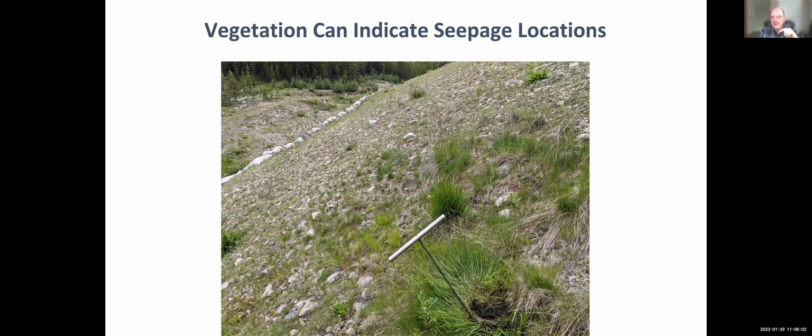And so the vegetation, you can use it as essentially instrumentation to indicate where there are wet areas on your dam, and that's going to require a more careful inspection of those areas on a go-forward basis. So here, the wet is by these. I'm not a grass expert, but these types of grasses, if the wet area is lower down, we often end up seeing cattails grow in those environments.